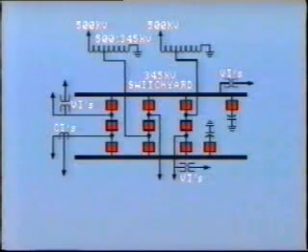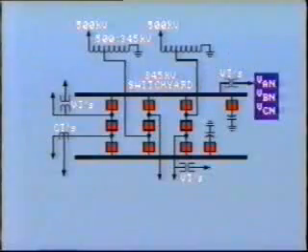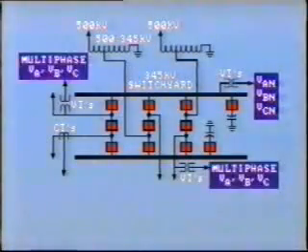Multiphasing comes in handy when we wish to monitor voltages on individual lines in addition to the bus voltage. A common arrangement would be to use a separate channel for each phase to neutral bus voltage, and then multi-phase selected line voltages.